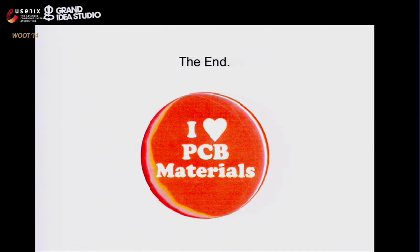So I'm guessing a bunch of people suggested this, but did you try just using a belt sander? Yes, a belt sander, drum sander sort of thing. I'm not very good with machines like that, which is why I went with the surface grinder instead, which is basically the same technique. That's also how I was trying to emulate with the Dremel tool. It will be good as long as you have good enough control of the board going through. Because if you're on a drum sander and you slip, you're going to eat right through. Between the copper layers is super thin. So if you're good at it, yeah, it will probably work.